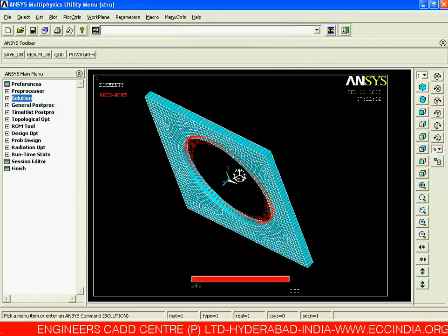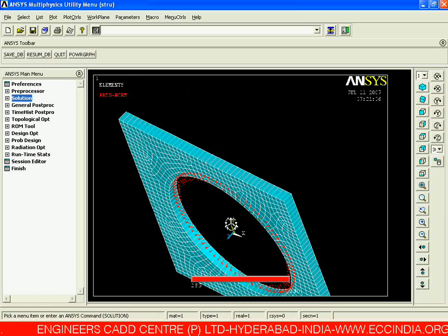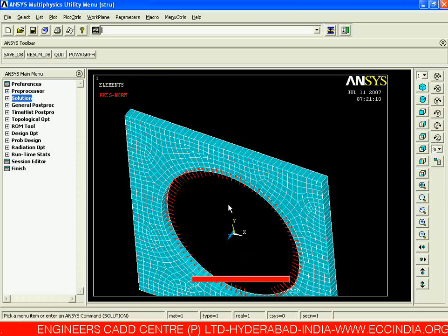Now switch on our elemental display with respect to the thickness value and just say OK. Once we are saying OK, we can check the difference over here. We are having a thickness of 1 with respect to that particular element. Thickness is assigned to only finite element entity. That means we are going to get a thickness in an elemental form only.